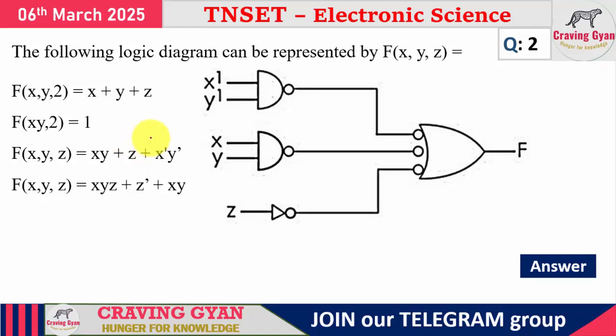In the second question, this question is from logic design or digital electronics, from the combinational part. This is x complement and y complement connected to a NAND gate. What we are going to get is x bar into y bar, the whole complement. Similarly, here we are going to get xy the whole bar. Here we are going to get z bar. What is the output at this end? We get x bar into y bar, the double complement.